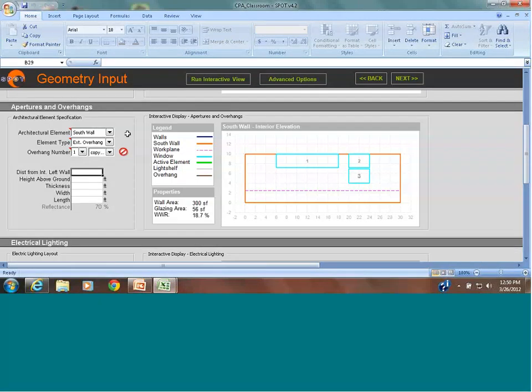And then when it comes to solar tubes, we can model it in a couple of different ways. We can model it as a skylight, as an opening on the roof, or we can model it as an artificial light, right? Because it does come with an IES file that tells us how the distribution will be. I didn't see anything for those under the aperture lens. For solar tubes? No, yeah.